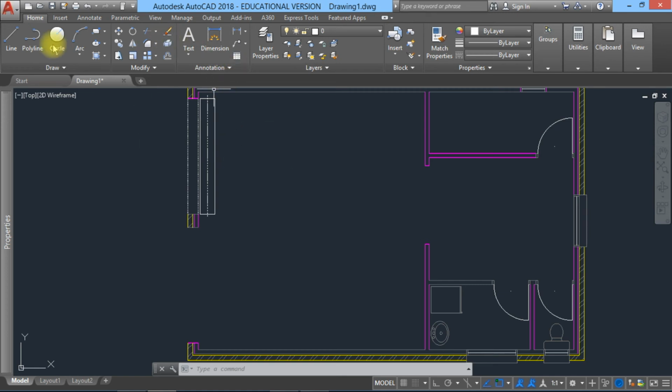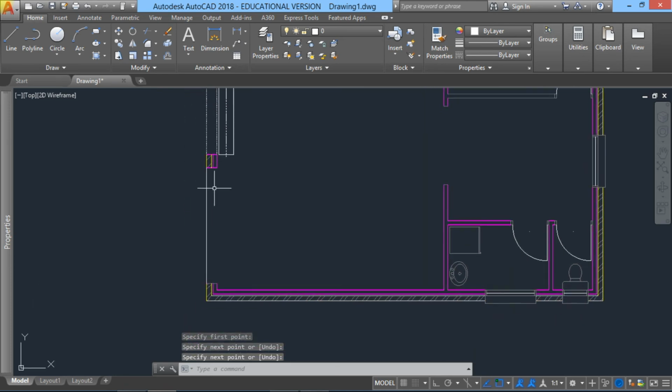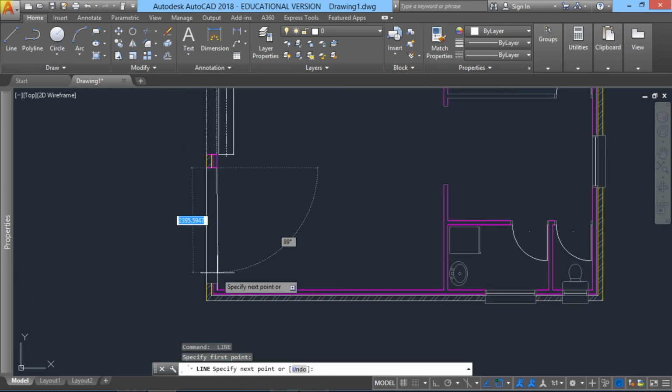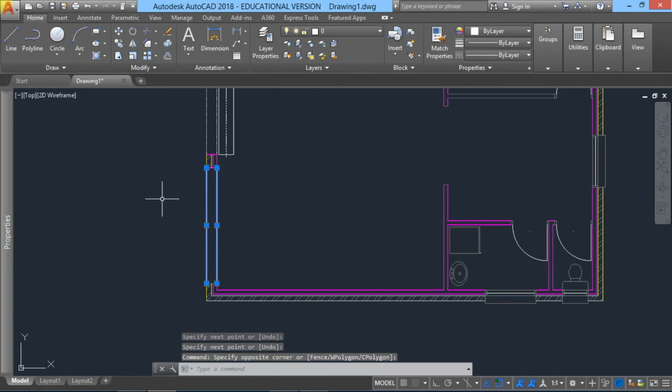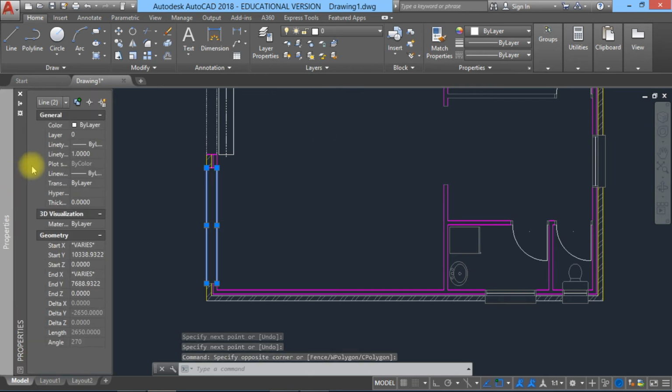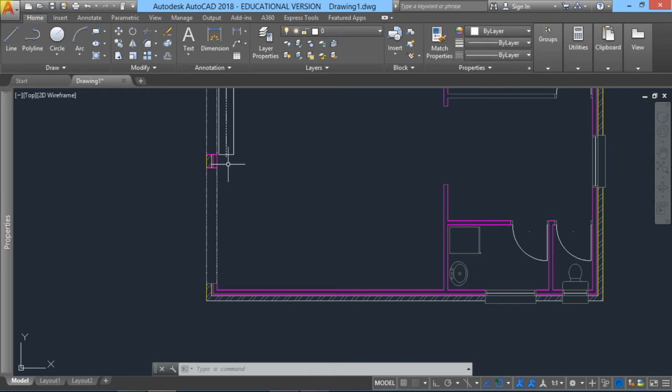Then in this case, firstly I should draw lines from each corner of the wall to the other corner, and the reason is I'm going to define the lintel on top of the opening. These lintels are drawn in the drawing layer, which is layer 1, but the line type is by layer, and I want to change it to dashed because we can't see them.